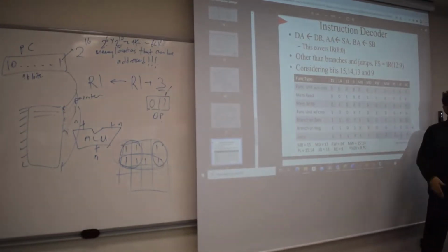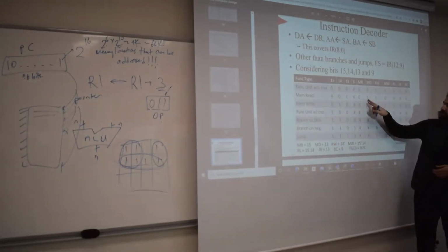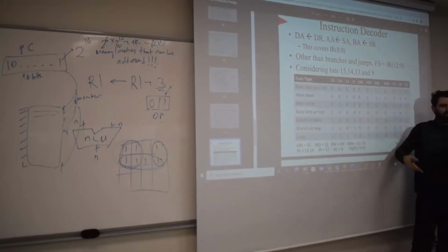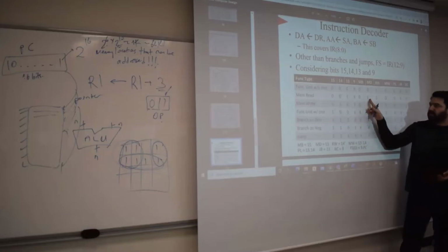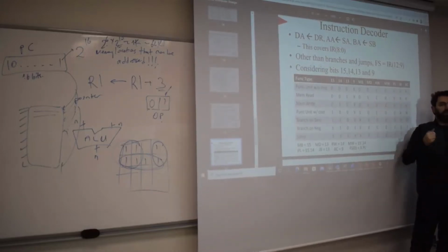MD is the last mux operator that has got something to do with the memory load and store. Okay? And so that's why we got memory read and memory write for this MD to be, for example, 1 and don't care. Okay? In the write case, it's a don't care because you don't use it. But for the read case, it matters. Right? You have to take that input and put it into your bus. Otherwise, it will take the function unit outputs.